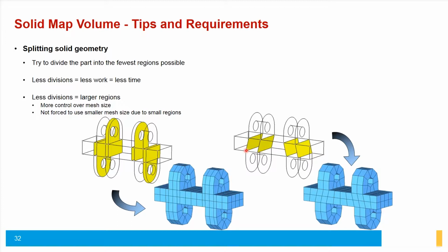But on the contrary, if you partition it at an angle, then you'd only have 4 partitions as opposed to, what is this, 6? So then you'd have your elements skewed off a little bit, but then you have fewer elements to worry about, right? Because this would have smaller elements going through it.